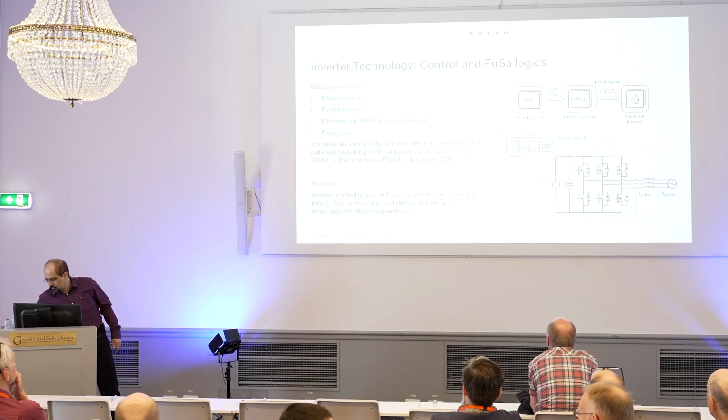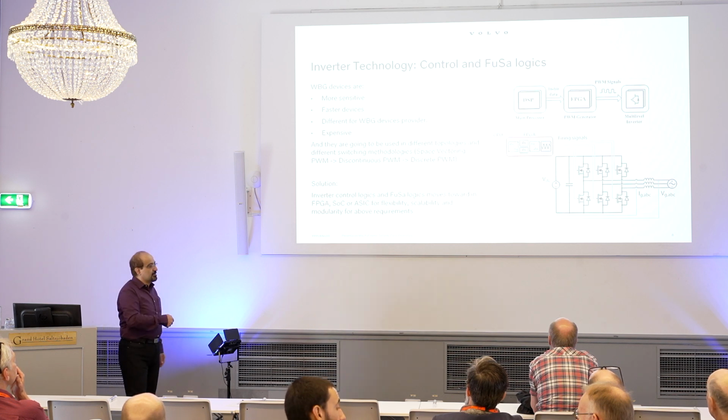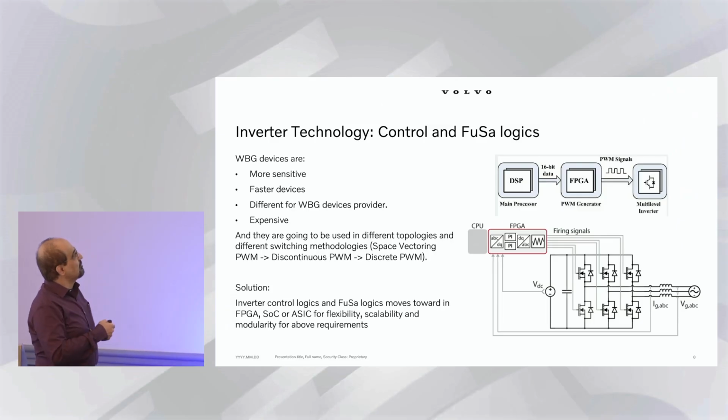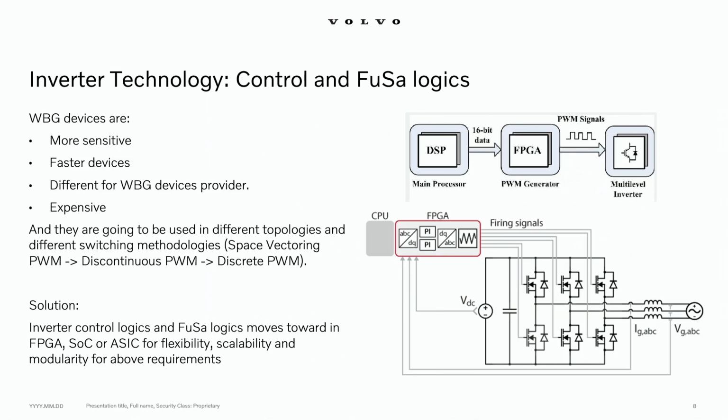And also inverter technology. Inverter technology also affects the control and firmware logics, as well as wide bandgap devices. We know they are very sensitive, fast devices, there are different wide bandgap device providers, and they are expensive. Due to that, when we talk about control and firmware logics, we need different topologies in this method, and also different switching methodologies.